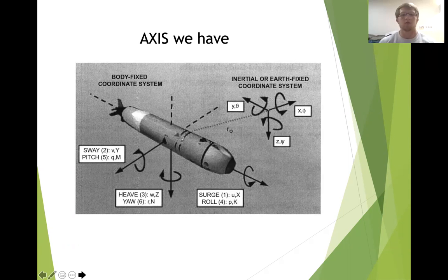From the Timothy Prestero report that Asher just mentioned, we got this graphic, which helps us visualize how we model our AUV. As you can see, there are 6 different degrees of freedom. There is translation and rotation about each of these axes, X, Y, and Z, each with a fancy name like surge, roll, heave, yaw, sway, pitch, etc. So to completely model this submarine, we'd need all 6 to be defined with transfer functions, but we decided to only model with 2. So next slide, I believe it's Kaiden.